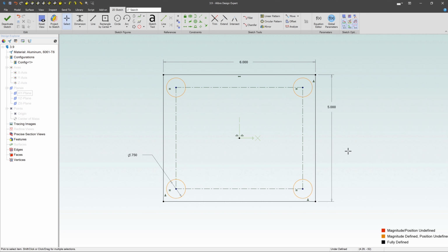Now think about how much work that would be if you didn't have this rectangle on the inside. You'd have to add some dimensions between each line, and you can still define this, right? You can keep adding dimensions here, and that's just fine because it's already been offset a 1/2 of an inch, but it allows you to quickly offset all those lines and eliminate all those dimensions you would have probably had to do before. And you can use offsets for a lot of different things. But this is one of the best ways to do that, offset and then switch over to reference geometry.